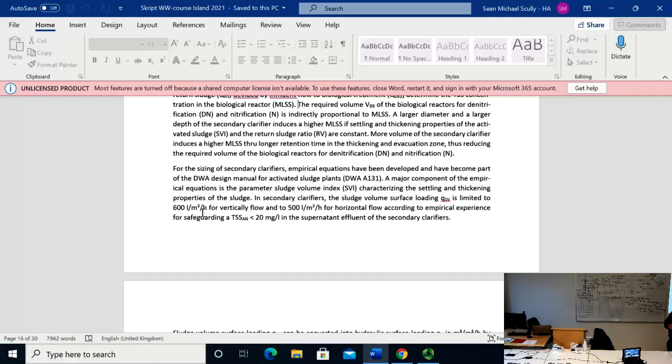And the return sludge volume you can just control by your return sludge pump, no? And you know your inflow, so you can look at this ratio of what you normally operate. In peak flow you try not to go over 75%, and in normal operation, when you have just average flow, you try to work with 100%, no? Not to have more, because then you don't need the full capacity.